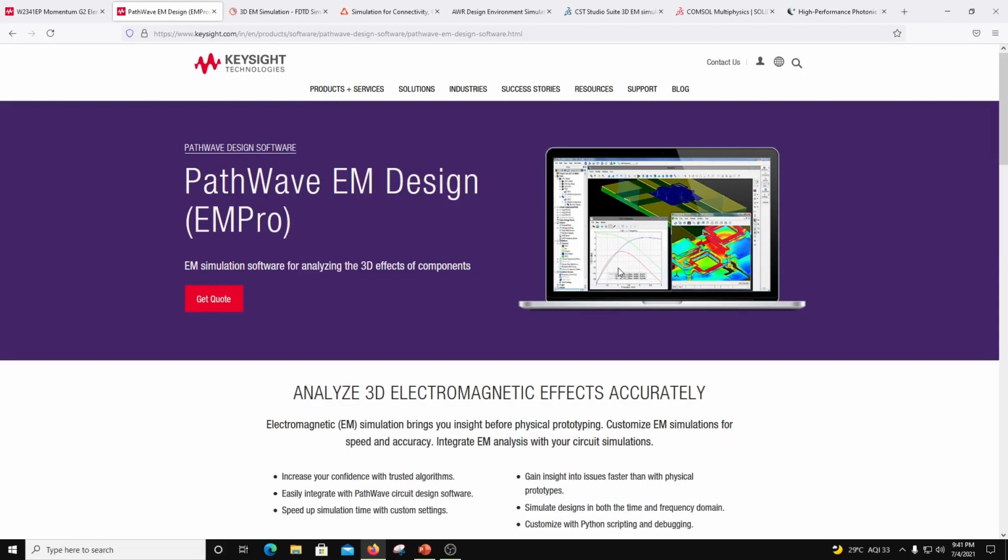So if you discretize a large object with cells which represent the smallest feature, then it is going to become very elaborate because the number of cells is going to be large. Now in that case, it is possible to do adaptive meshing. So in finer features you can use smaller cuboids, while in bigger features you can use bigger cuboids, and then you will be able to do the interface.